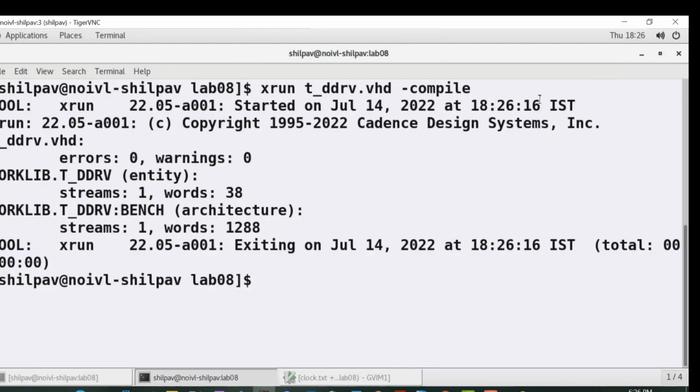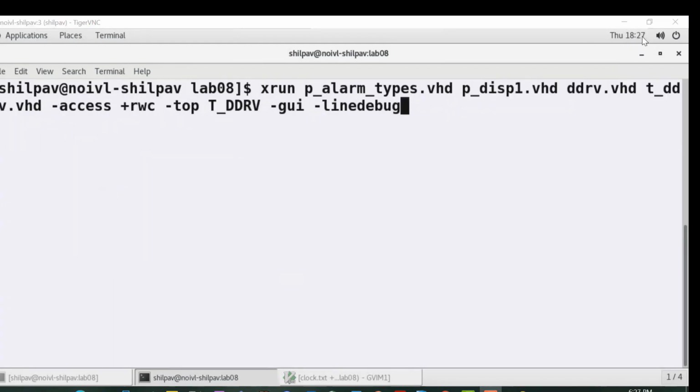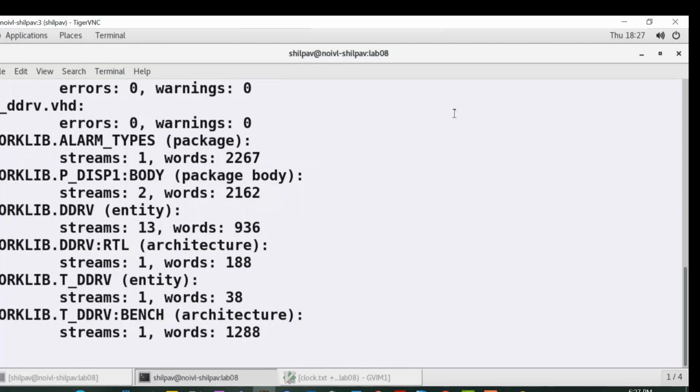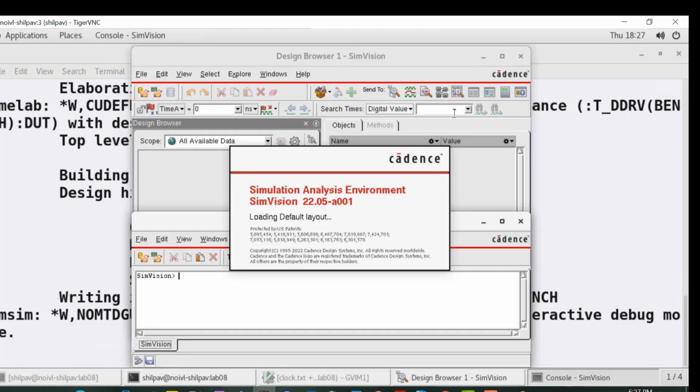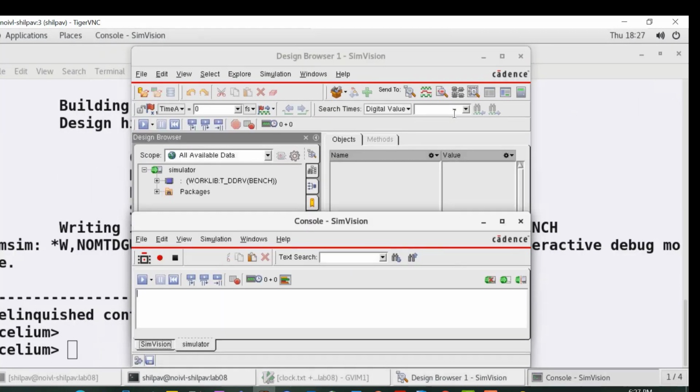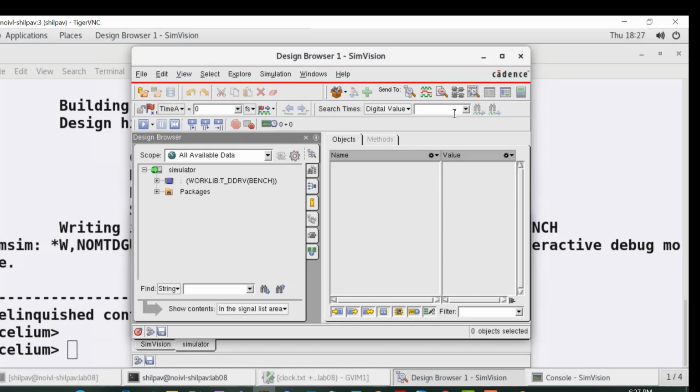Compile this file to check for any syntax errors. Let us simulate the design. The testbench will create a file called clock.txt containing a character representing the 7-segment display. View the clock.txt file in an editor. You may need to keep refreshing the file to see the changes in the output. Run the simulation in short steps so each output value can be observed in the 7-segment display.